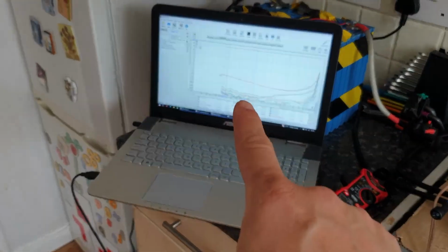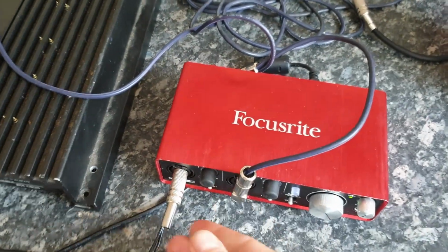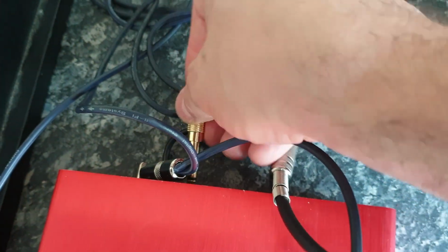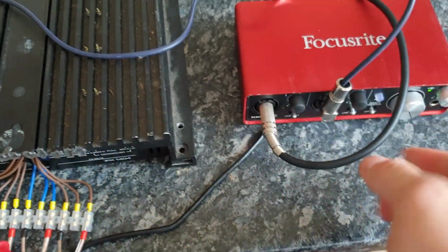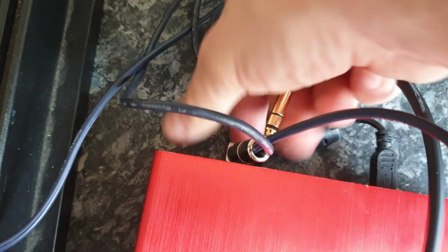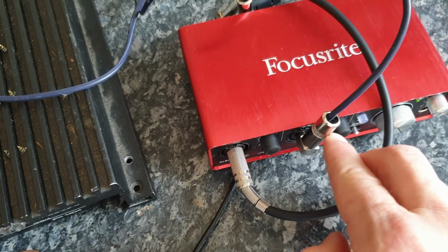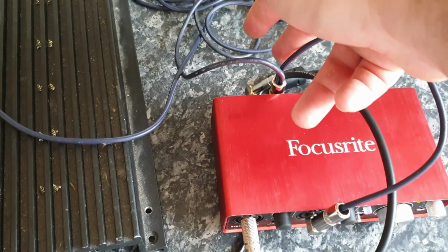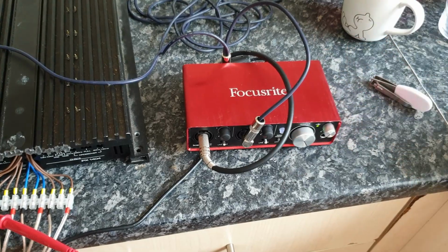Oh, one thing that I forgot to mention, because I will be showing the actual measurements of the interface. When I'm testing this, it's testing the amplifier. When I'm testing the interface, I need to disconnect this one and connect another loopback instead, because I need one. I know you like all the small little details, so otherwise it's just going to be confusing. So basically output 1 into input 1, output 2 into input 2, and it's basically the interface measuring itself, its self performance. It measures how good of an output it is. So this is just two loopbacks, for self measuring.